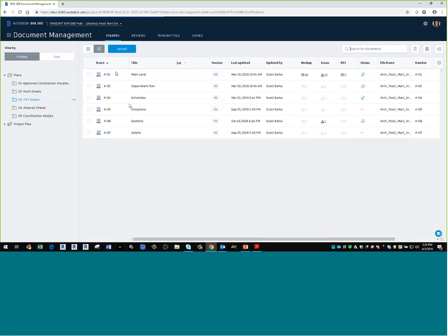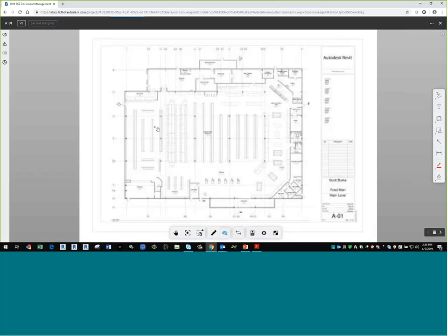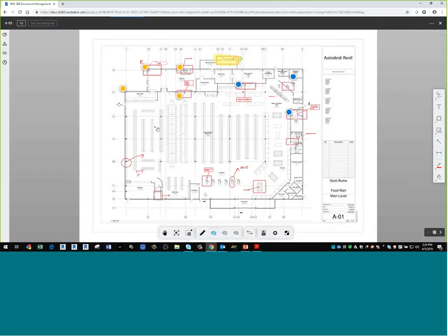And then I can select each sheet individually. That way, if later on I come in and I update the set and add an 8 to it, at sheet 8, then sheets 1 through 7 would actually be version 2, and sheet 8 would actually be version 1 within the same document. So these are all really powerful tools that really allow you to leverage these models to make this truly a paperless workflow, both in the office and in the field.